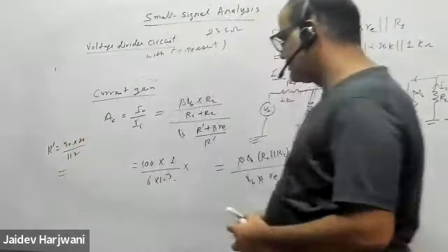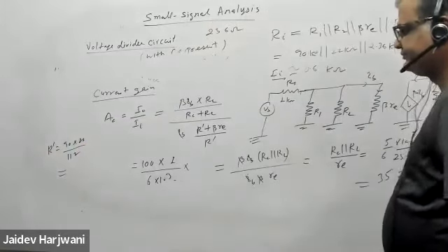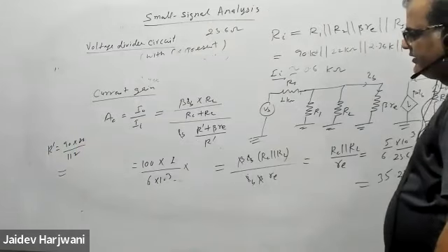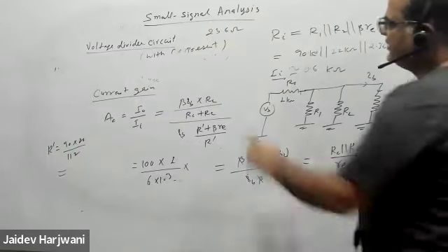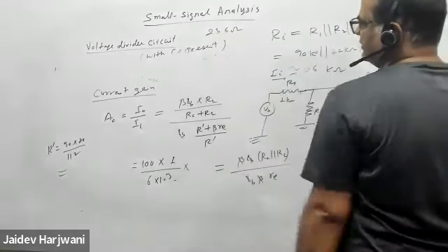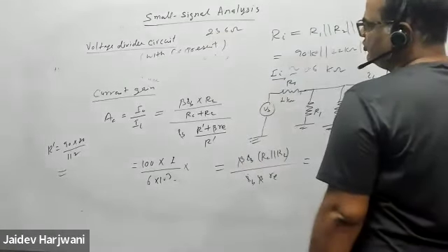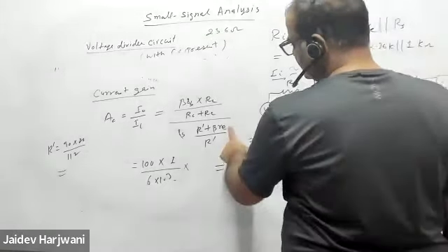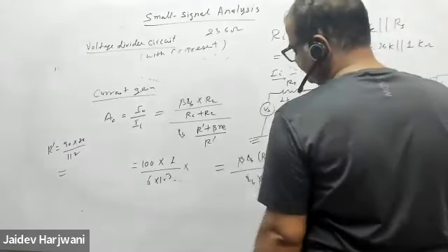What is the value of R dash in kilo ohm? Plus beta RE. Beta, this is 23.6. Okay, so multiply by 100. So it will be 2.36 kilo ohm. So R dash plus 2.36. Tell me how much is coming.